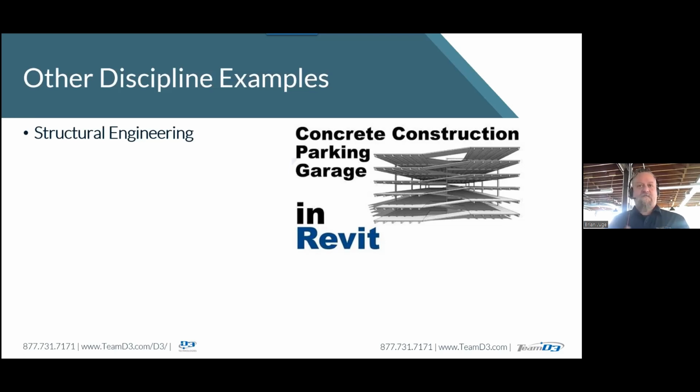parking decks and stuff. But I found that I'm relying a lot more on the environment tools to help me out, to do reference surfaces, to put that in there, and to make this a lot easier, especially when we're going real technical and I need to have that ramp make my 3 degrees, 5 degrees, 15 degrees to make that transition up in there. And I'm doing it on a curve at the same time. And this has really helped out with that.